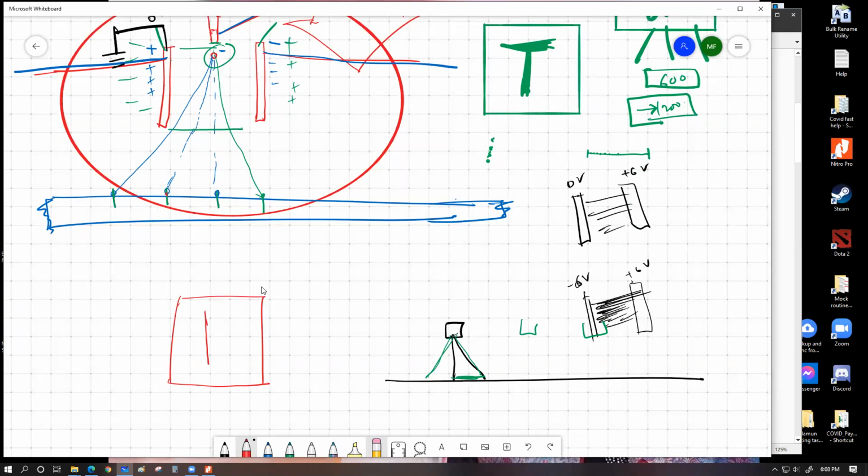To make a single straight vertical line, we should logically have the same voltage across these two plates for the entire printing process, right? Yes, sir. Because now, if these droplets do not have the same charge, then the one that is more charged will be repelled more to the left, and the one that is less charged will be repelled less to the left. So you're not going to have a straight line. What you're going to have is a zigzag line of droplets. More charged particles are going to bend more, less charged particles are going to bend less. So we cannot have a precise location.